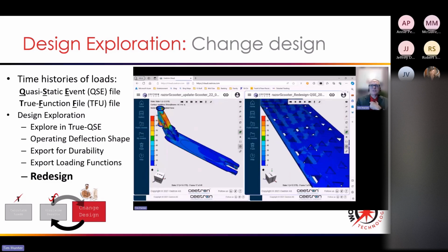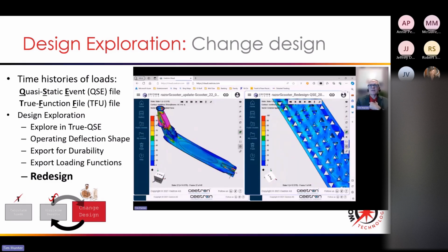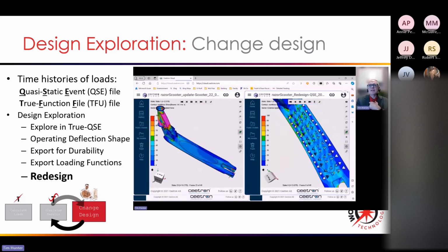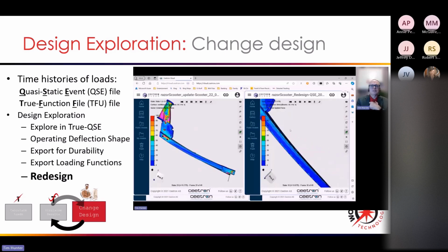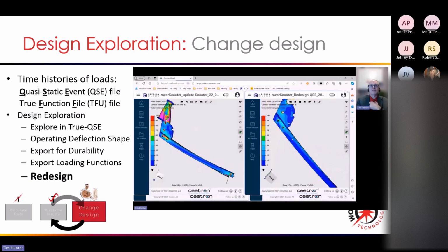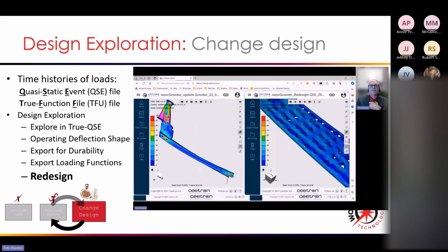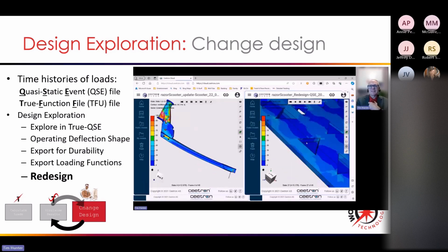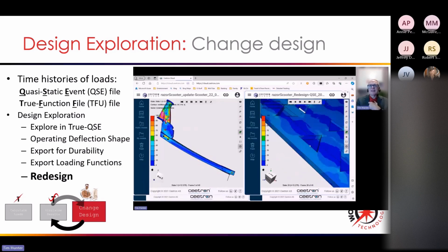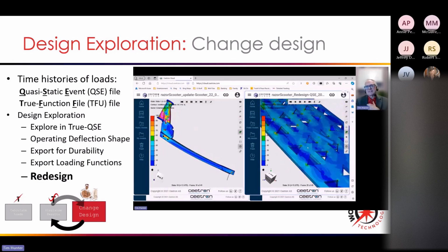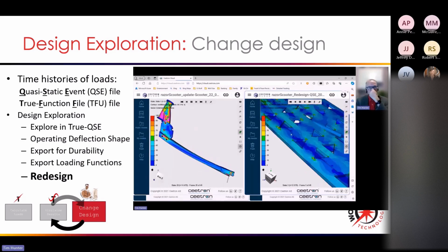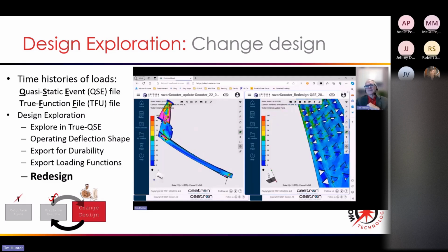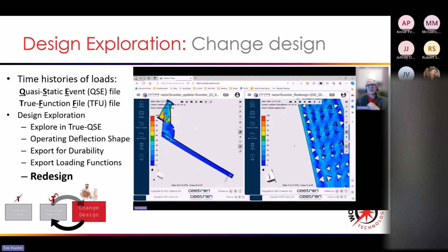And yes, we get stress risers here. We get some increased stress because of my cutesy little pattern. But nominally, that's not a big deal. It's nothing that we'd be too concerned about. Everything is basically performing more or less the same. The only concern I would have on my design is these points in my triangles. I've got stress risers going on there, right? So if I were to finalize this design, I'd probably want to put some fillets in on those triangles to take out those stress risers. But that's totally doable, okay? I didn't want to futz around with the CAD anymore, but you get the idea.